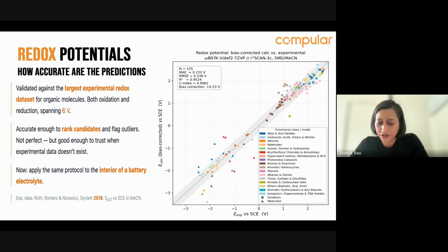So using our simulation tools, you are able to screen a huge number of different formulations that you might otherwise have to do physical testing for, in a matter of a couple of hours, and sometimes even 1 or 2 days. You can use our software to predict different material or liquid or electrolyte properties, such as transport properties, the salt diffusivity, different thermodynamic factors and properties, as well as predict the stability of a system, the redox potential, the electrochemical stability voltage windows, as well as see how your liquid performs at a constant potential when it's confined in a